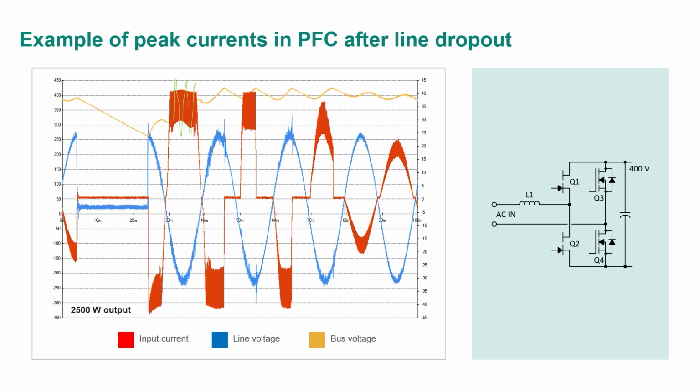And remember, I mentioned saturation earlier. Well, the saturation could drive this even higher, right? So I have to know what my real inductor current is, how high these peaks are, because I could be bumping up against the device rated limits, and I want to avoid that, because otherwise it's going to desaturate and go into a thermal runaway condition.